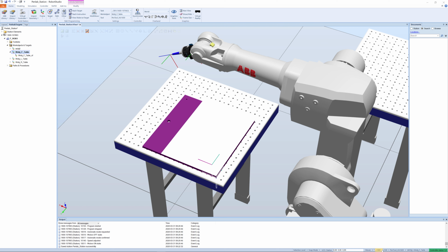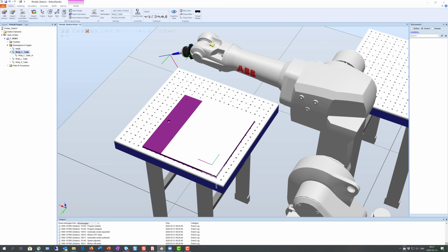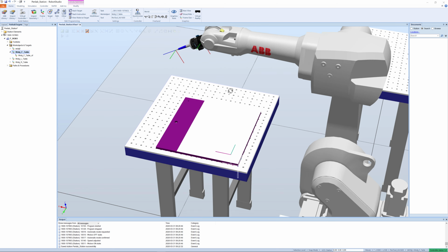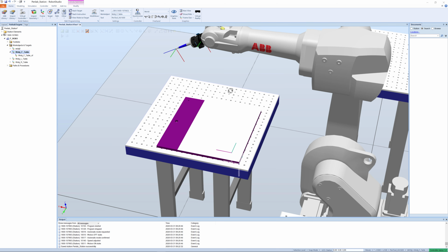Velocity from the beginning is 1000. It could even be higher for the via motions, but when we draw, we go with, say, 100 millimeter per second, so we get the drawing in a nice way, and we can see what is happening. The pen tool is fine as it is, and the work object front table. So everything is fine. We do this. Everything else we can add later on. So that's fine.